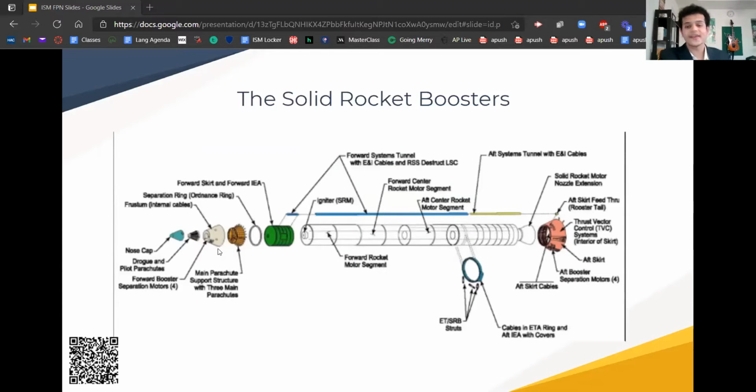All right. So before beginning our discussion of the different ascent procedures and abort modes, the engineering of the solid rocket booster is worth noting. The SRBs are actually kind of rockets themselves, and they are fueled by solid propellants. Solid propellants really gained traction because of the high amounts of power that they're able to deliver with the same amount of fuel as compared with liquid propellant. The two boosters carry the entire weight of the external tank and the orbiter and exerted about 2.8 million pounds of force to get the vehicle up to an altitude of 15,000 feet in a mere 2 minutes. The solid rocket boosters were 69% of the total liftoff mass of the vehicle, so it was a significant portion of the mass as well.